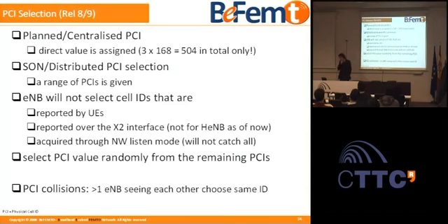It's all good, your UMTS network may just do well, LTE maybe as well, but as you start introducing femtocells, you get very quickly into collision. So you may assign the very same PCI to nodes which are in a neighboring relationship, and this is causing a lot of problems mainly for the mobile terminal, because it doesn't know where to go, essentially. It has a PCI which is the same.